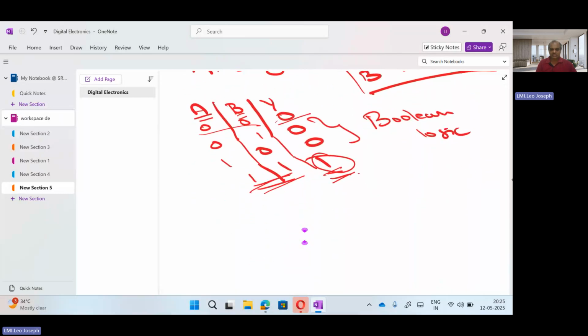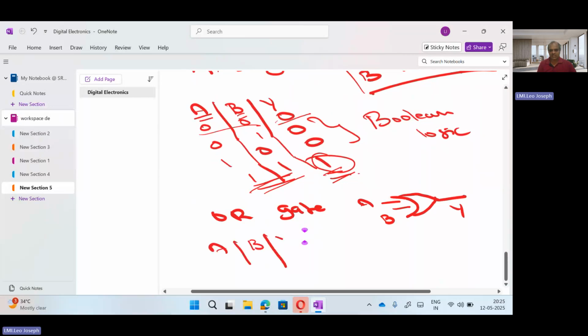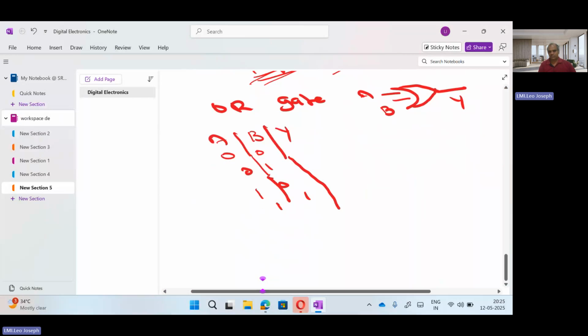So the OR gate, the same thing, and the OR gate symbol will look like this. Similarly A, B and Y. If I write the truth table, I will get it like this: A, B and Y. So 0 0, 0 1, and then I can write 1 0, 1 1. Sorry, my handwriting is somewhat slanting, so I will try to rectify that. So here 0 0 means 0, 0 1...